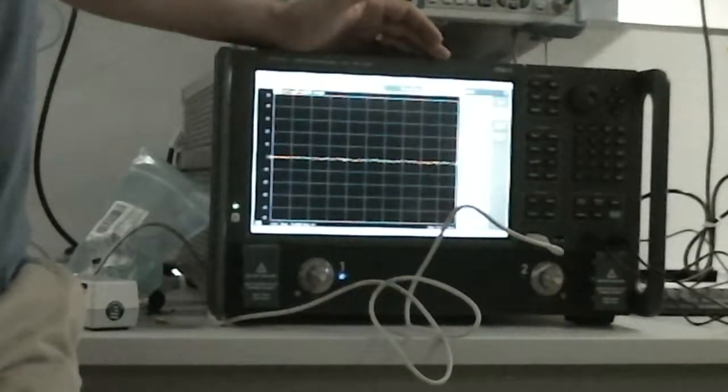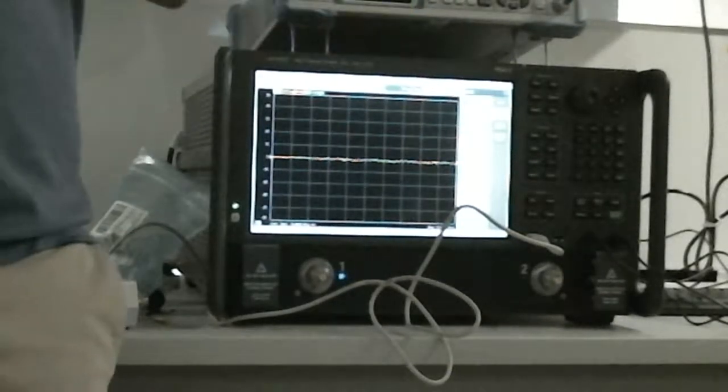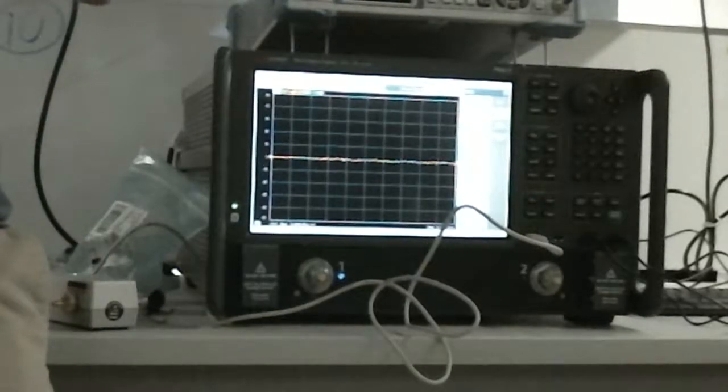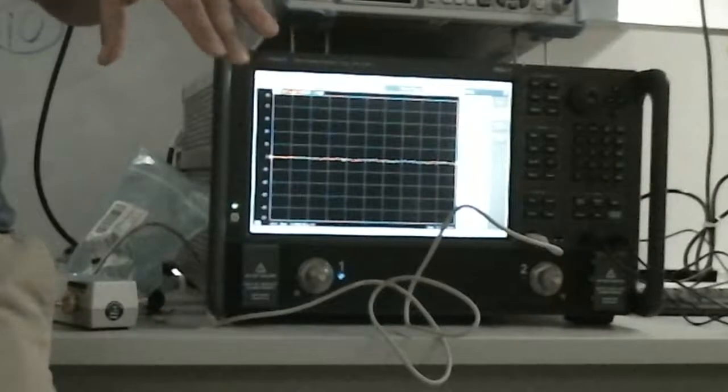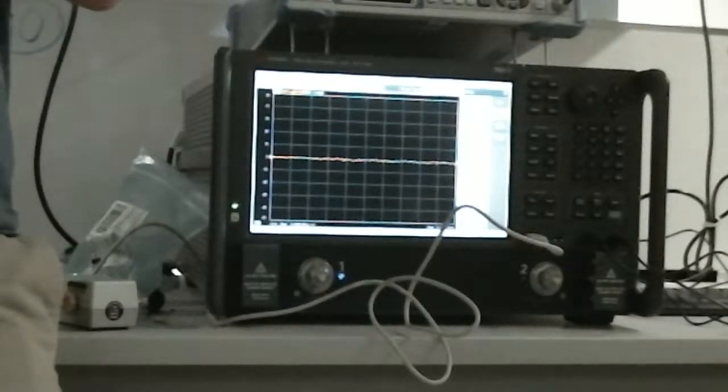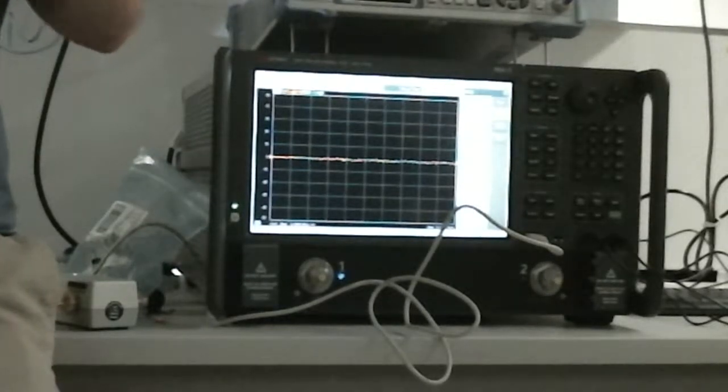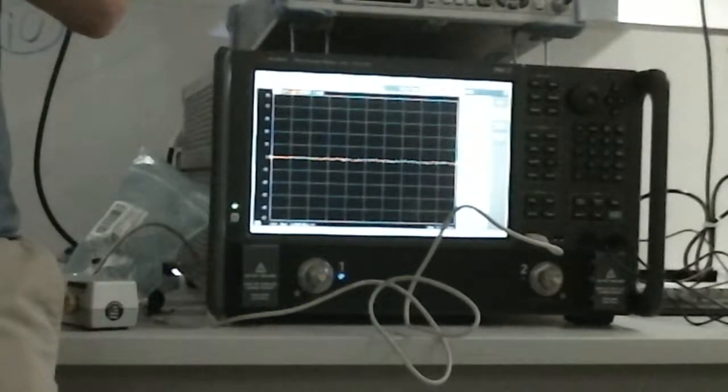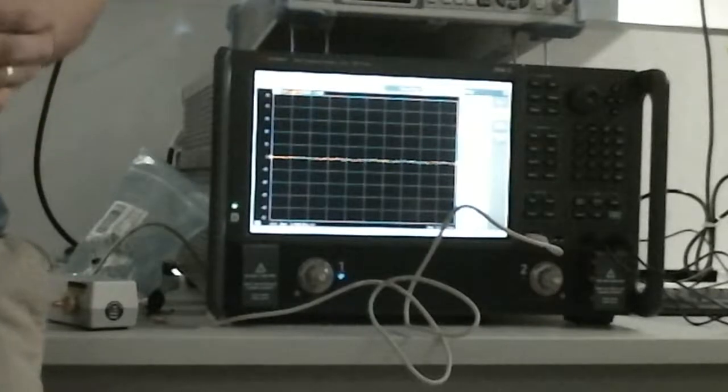It will not increase the number of points, but at each frequency point it digitally filters the measurement more and rejects the noise out of the measurement, right? Remember, on the receiver side you're just looking at the received signal within a certain bandwidth. If you narrow the filter you're using, your signal to noise ratio is going to get better because the signal is the same. By reducing the bandwidth, and the noise of the receiver is flat with frequency, we can assume it is, as we reduce the bandwidth by a factor of 100, we've improved our signal to noise ratio by 20 dB effectively.